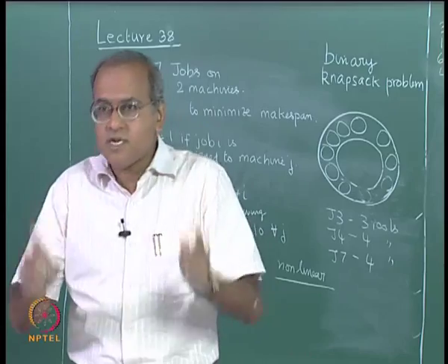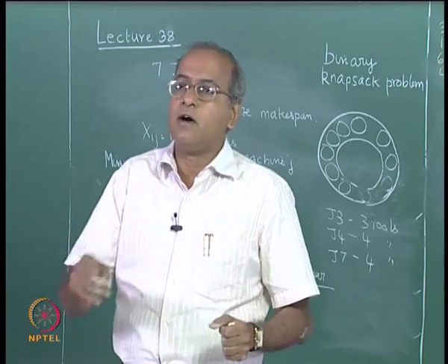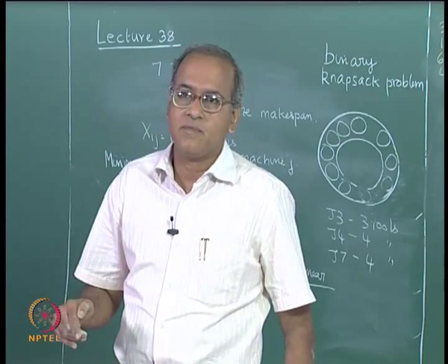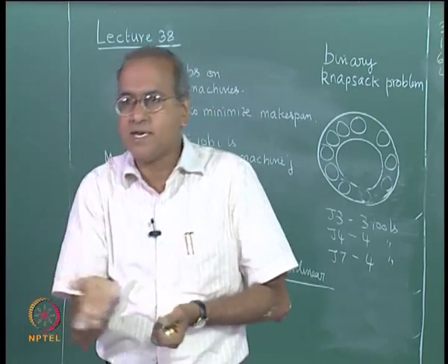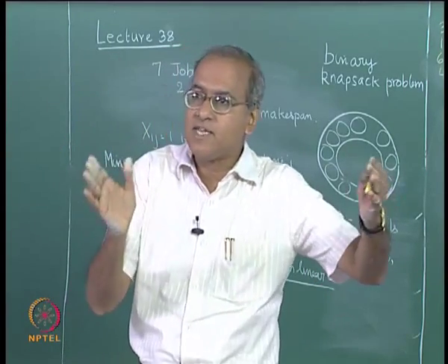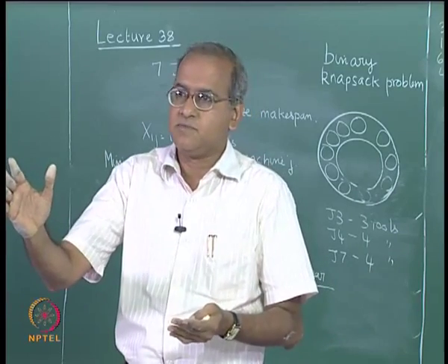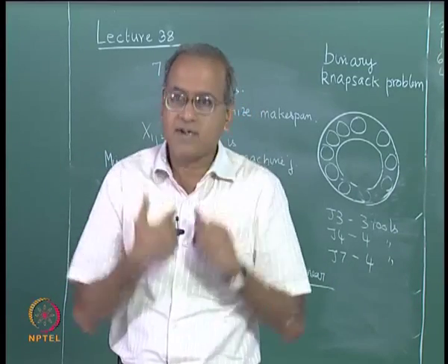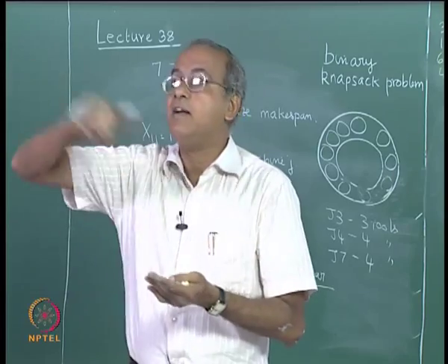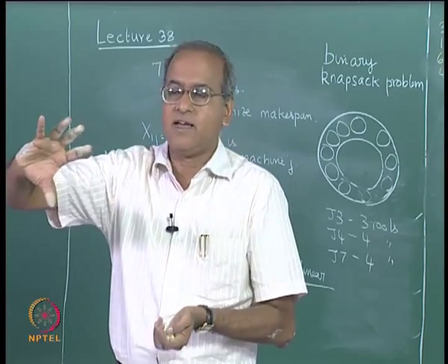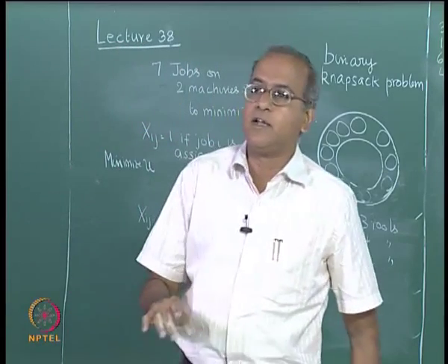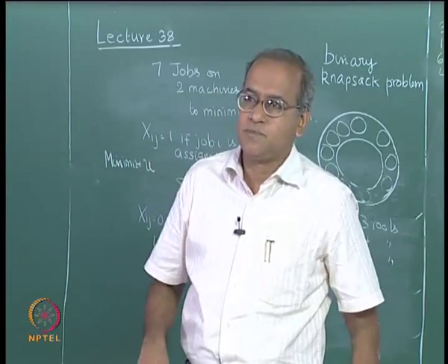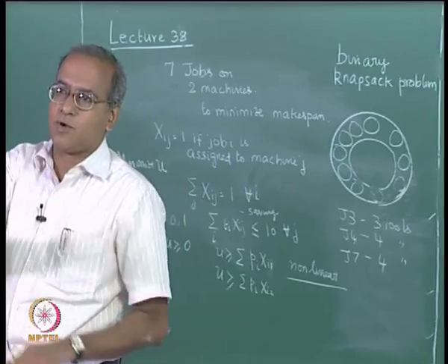So the first 10 jobs will have to be run in multiple batches, because the 10 tool slots will now be set up, a subset of these 10 will be done with this, and then the second part of that 10 will have to be done again when these tool slots are either retained or some changes are made to this depending on the requirement of the other jobs. So there is also a batching problem.